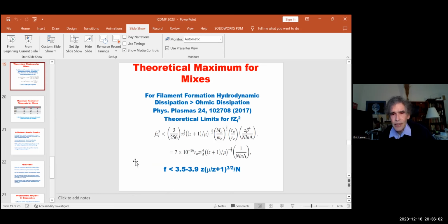They're producing 2 pairs of filaments per tooth. So we're getting 128 filaments, which is too many. So we think if we just reprofile these teeth, which can be done without creating a whole new cathode, we can reduce the number of filaments and therefore increase the amount of current per filament.